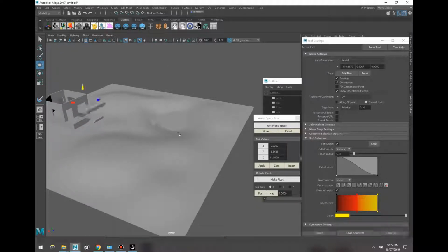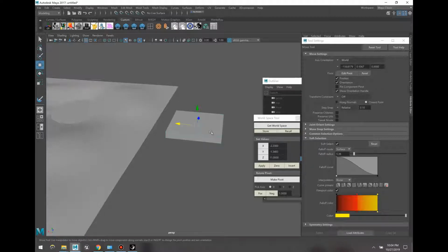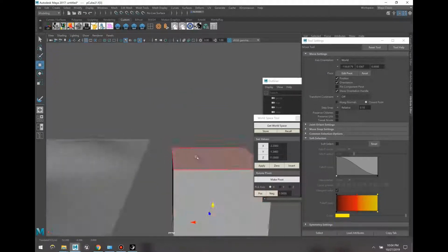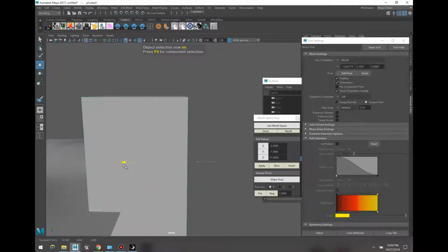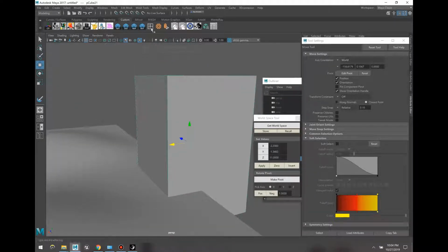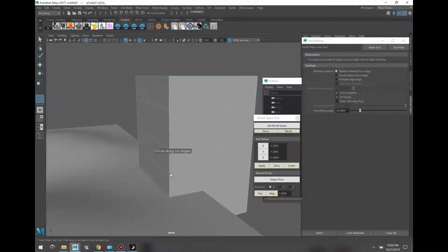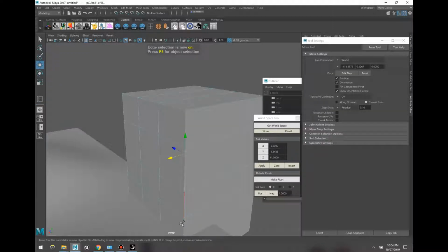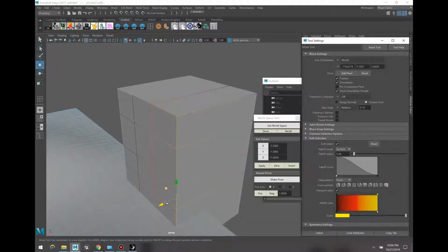And the way to do that is, let's start with an 8x8 kind of mesh. What I like to do here is, if I turn off soft selection, I'm going to build a rock or a mound, and all it takes is some subdividing, and then sure, some soft select. So here I'm going to hit F10 and go to edge mode. I'm going to go to soft select. And then let's turn that down slightly.